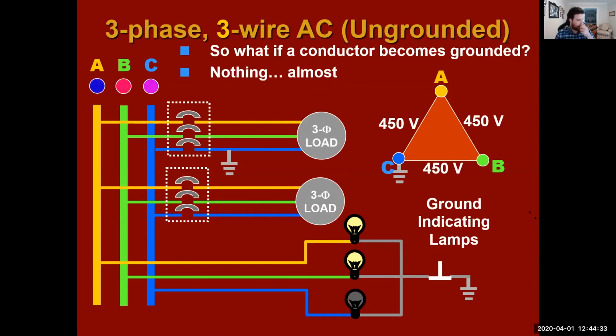So last but not least, and this is the last thing, I'd appreciate it if you guys just stay for another minute. This is where it gets bad. If you have two grounds on two different wires, this is when you can actually have a problem. Because remember, like I said, this ground right here and this ground right here, you might as well have a damn wire connecting both of them. Take a jumper and put them together.